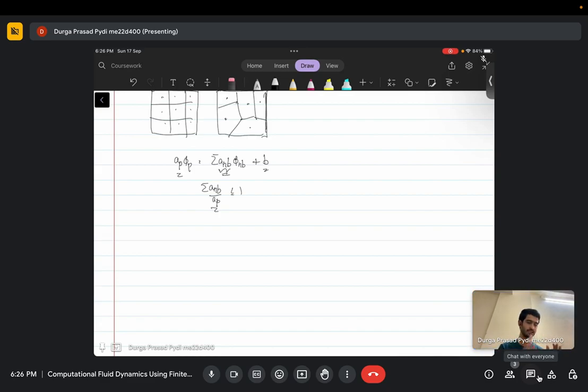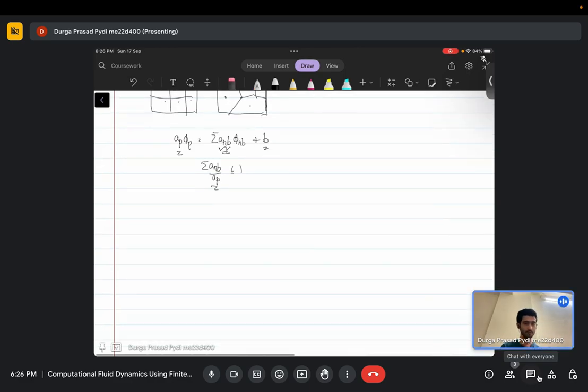Okay, there are two things. Even if you consider it without secondary gradient, even in structured meshes, if your time step is much larger, then your solution diverges, right? So does that mean the structured mesh is wrong? It's just that the way you solve it, it's the problem with the numerical method, nothing to do with the original problem.